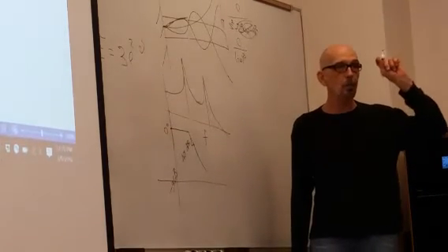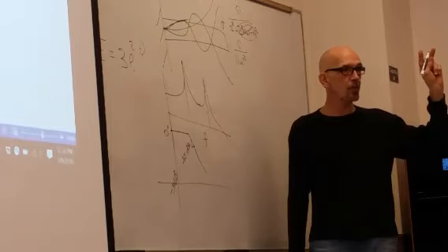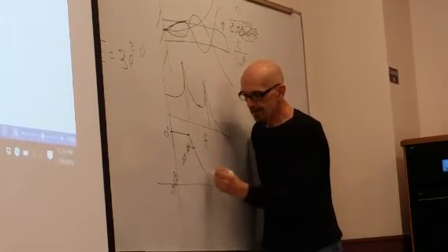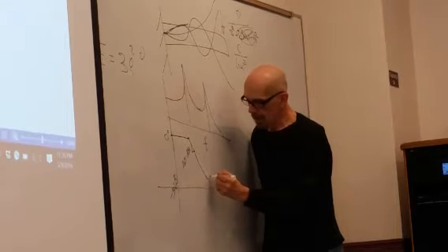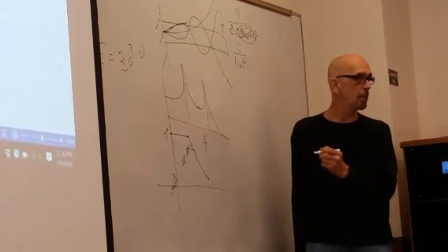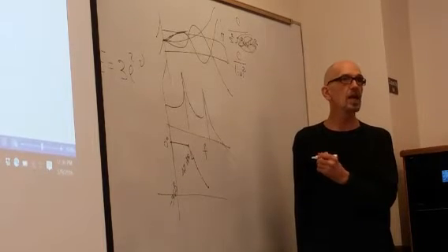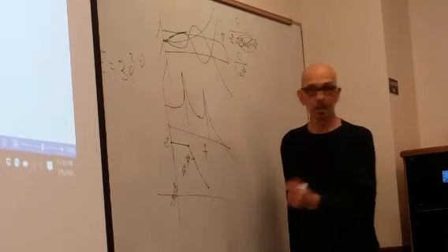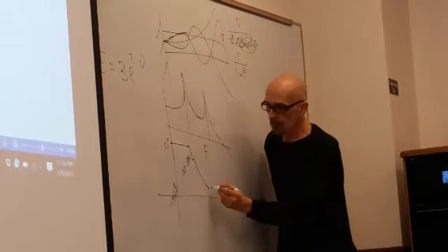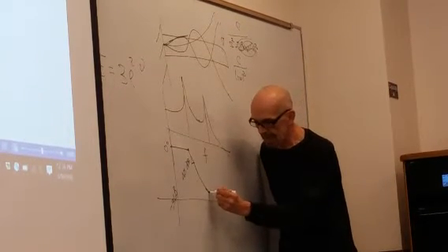All you do is work at the break frequency. There are two break frequencies. The first one is at omega n1, breaks down at 40, then you hit omega n2, and what happens? You get another 40, because you now have s to the fourth in that plant. So this goes from 40 down to 80.